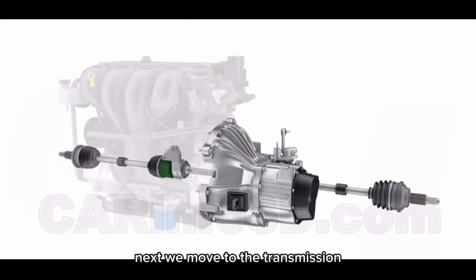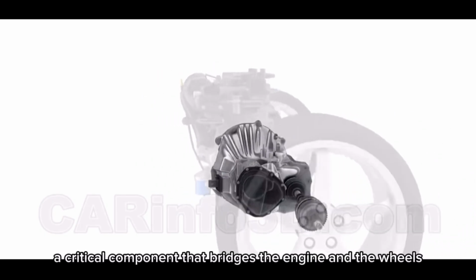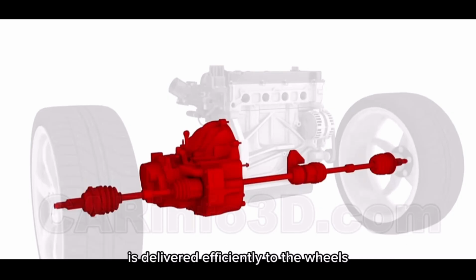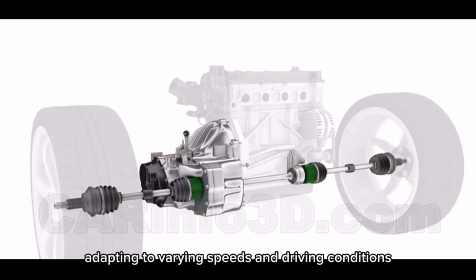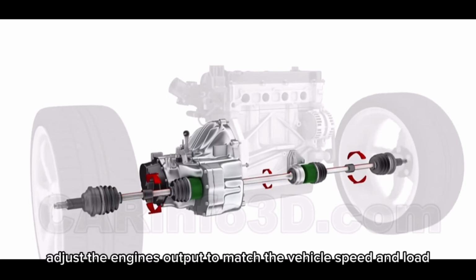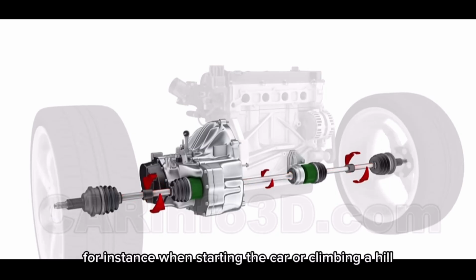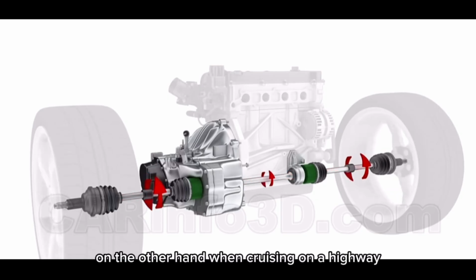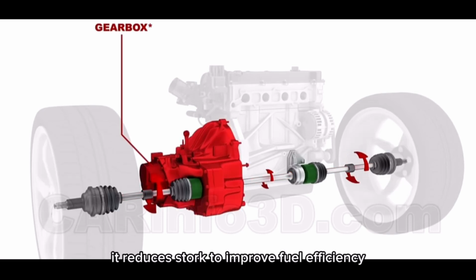Next, we move to the transmission, a critical component that bridges the engine and the wheels. Its main function is to ensure that the power generated by the engine is delivered efficiently to the wheels, adapting to varying speeds and driving conditions. The transmission adjusts the engine's output to match the vehicle's speed and load. For instance, when starting the car or climbing a hill, it increases torque to overcome resistance. On the other hand, when cruising on a highway, it reduces torque to improve fuel efficiency.